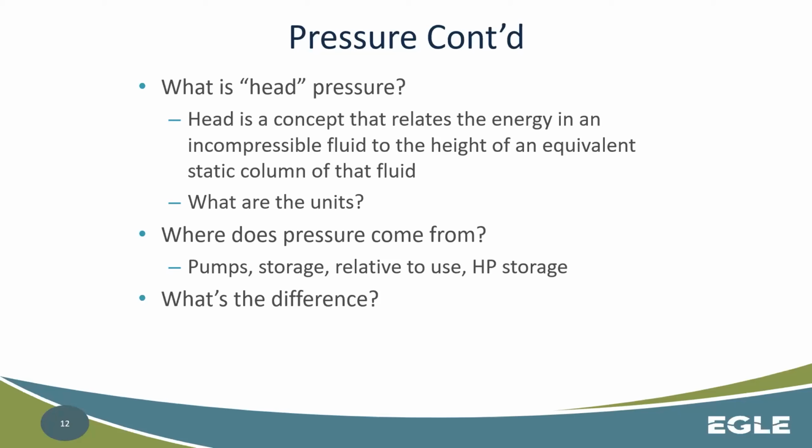The pressure in the pipe will make the height of that water rise in the tube, and this height is associated with a certain pressure. So the higher the pressure in the pipe, the higher the water level will rise in the tube. As I decrease the pressure in the pipe, I will see a water level drop in our observation tube.